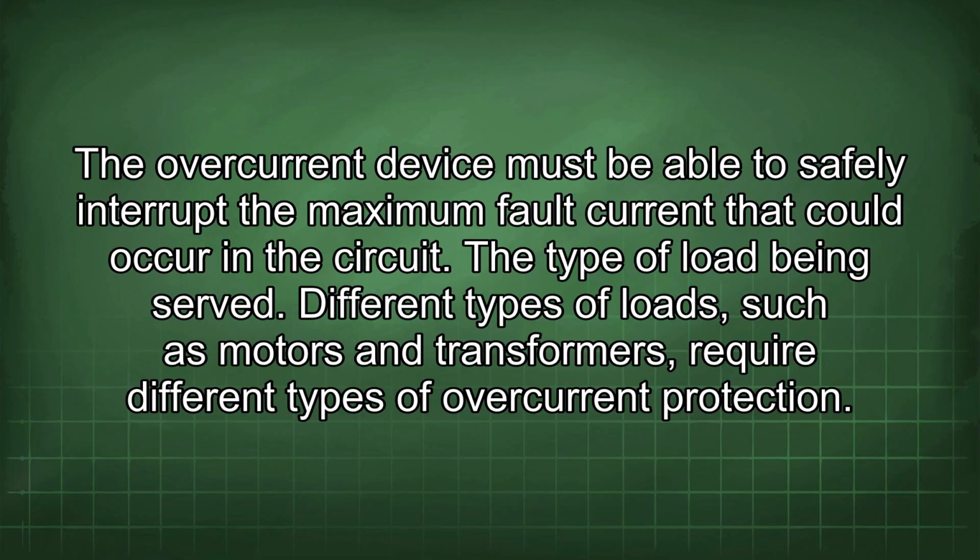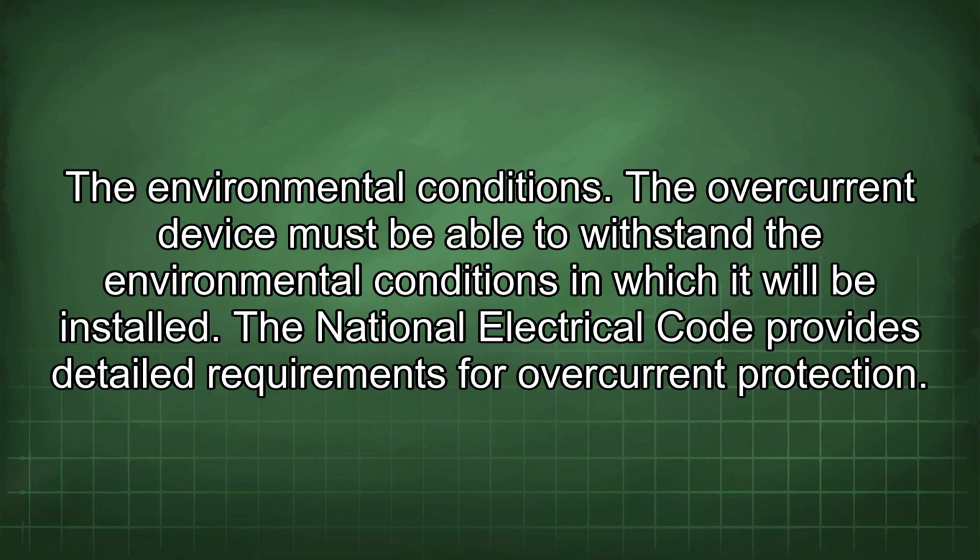The type of load being served. Different types of loads, such as motors and transformers, require different types of overcurrent protection. The environmental conditions. The overcurrent device must be able to withstand the environmental conditions in which it will be installed.